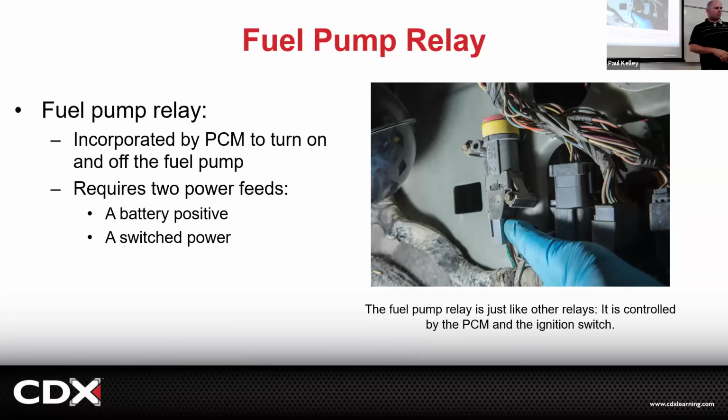Additionally, sometimes there's what's called an inertia switch. Back in the day, and I'm going to pick on Ford right now because I can, these Fords were having issues where they would get rear-ended in an accident and the fuel pump would keep pumping. Next thing you know, you might rupture a fuel line and the fuel pump would keep pumping, right?